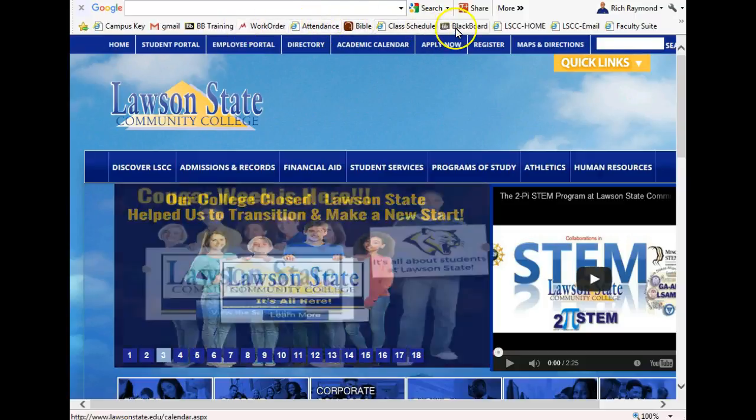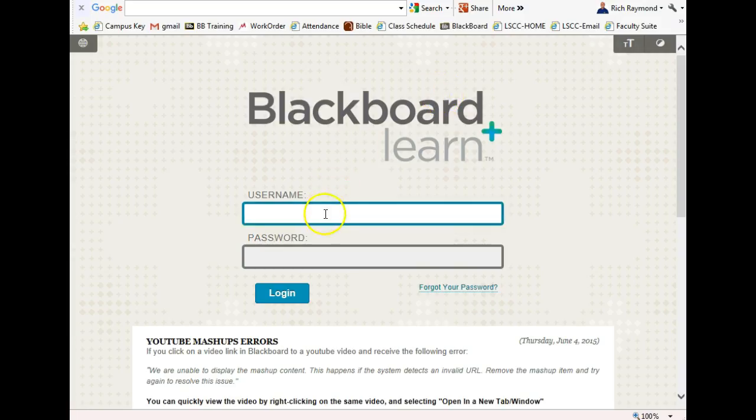Let me look at it. For one whole cycle? Yeah. So a cycle would be 30 amps, and we're not even doing that. So this guy here has no problem charging that capacitor up. Now once the capacitor is charged up, then it never fully discharges if we choose the capacitor the right size. Does that make sense?